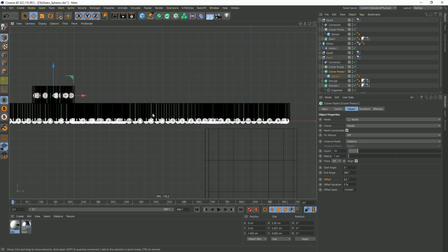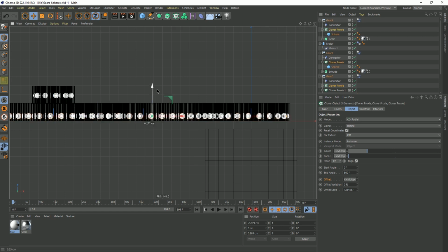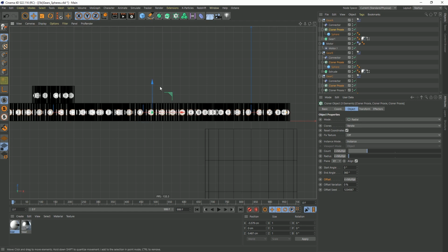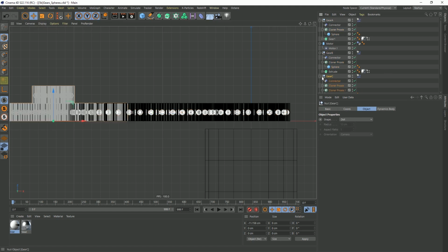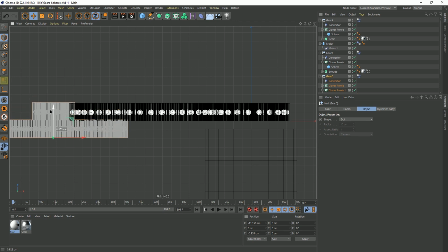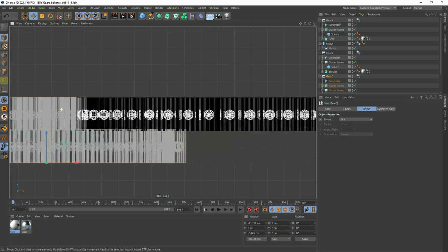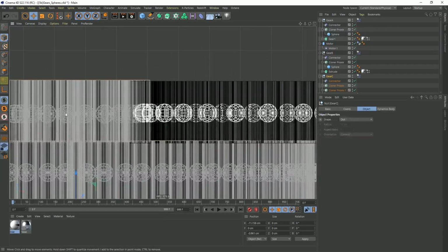Visually, it would still run, but I would like them to line up a little bit better. So I'm going to grab this chain of clones, that cloner proxy, all the big loops of them, and just scoot them all forward. In fact, we can center them inside of those gears. So we'll work at everything being in the center from here on out. If we have our final gear, gear C, we want these small ones to be what's lining up with those front ones. So scooting those in place, that should be working quite nicely.